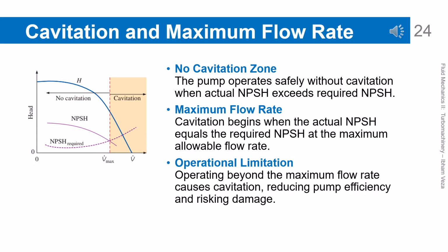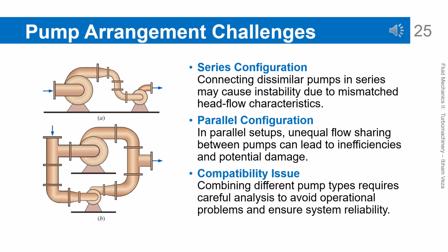Therefore, the maximum pump flow rate is often limited by cavitation rather than by the motor. Pump arrangement challenges. Combining different pumps in one system can create various operational problems. In a series configuration, differences in head flow characteristics can cause instability. In a parallel configuration, unequal flow sharing can cause some pumps to operate outside their safe limits.